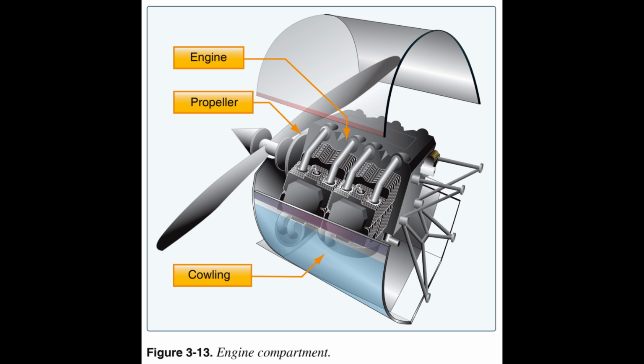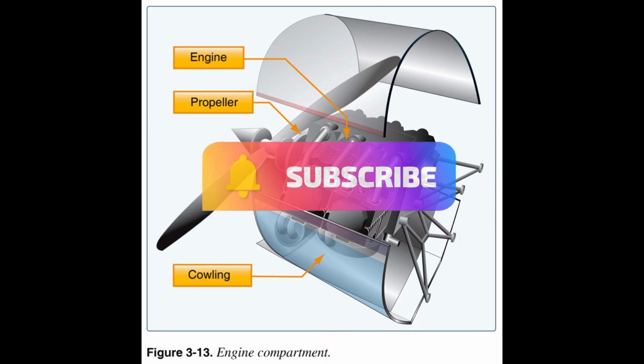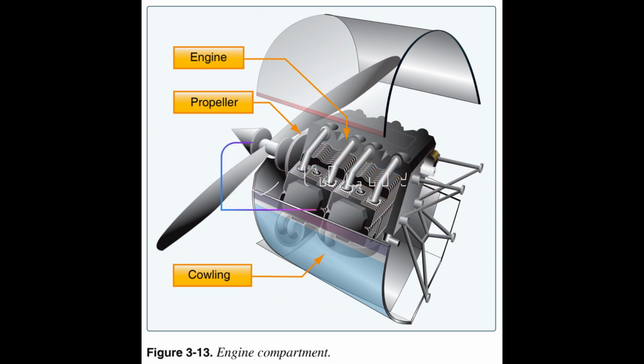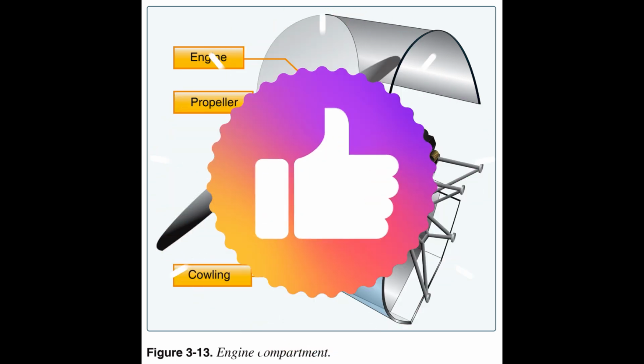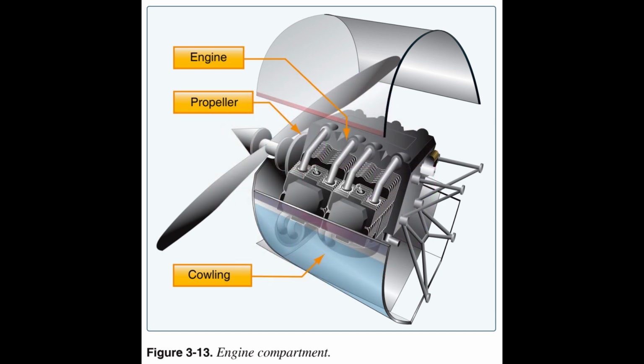In the case of most modern airplanes, airplane brakes consist of multiple pads, called caliper pads, that are hydraulically squeezed toward each other with a rotating disc, called a rotor, between them. The pads place pressure on the rotor, which is turning with the wheels. As a result of the increased friction on the rotor, the wheels inherently slow down and stop turning. The discs and brake pads are made either from steel, like those in a car, or from a carbon material that weighs less and can absorb more energy. Because airplane brakes are used principally during landings and must absorb enormous amounts of energy, their life is measured in landings rather than miles.